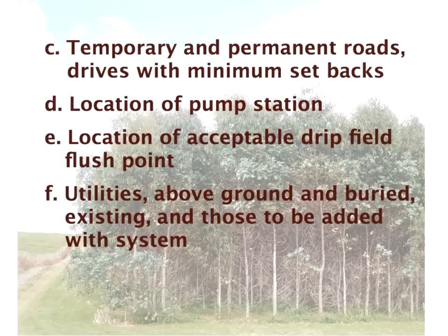where there's been compaction, and then the road's been abandoned, and it just looks like a normal piece of ground, but in actual fact you have a compacted strip across the prospective field, and sometimes you don't find that until the contractor goes in and starts plowing it up.